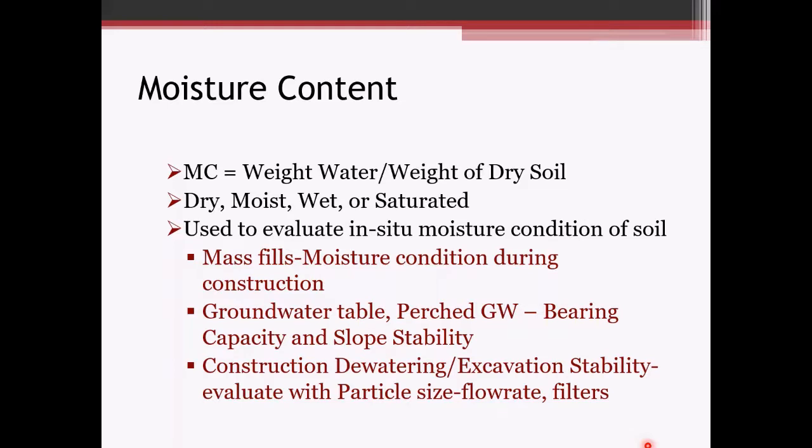And moisture content's important. If you have a site where there's going to be mass cuts and fills, it's important to know what the in situ moisture content is. That way, the contractor can have an idea if they're going to have to add water or if they're going to have to dry the material out as they're placing and compacting fill across the project site.